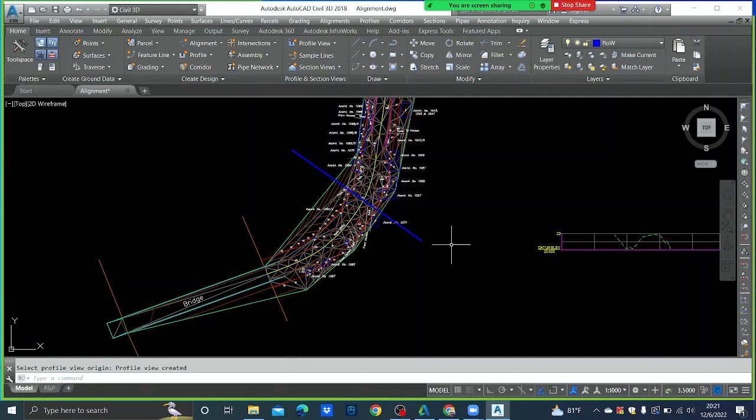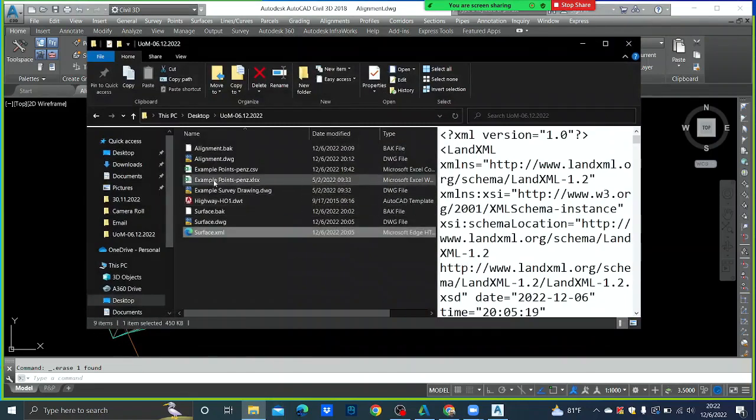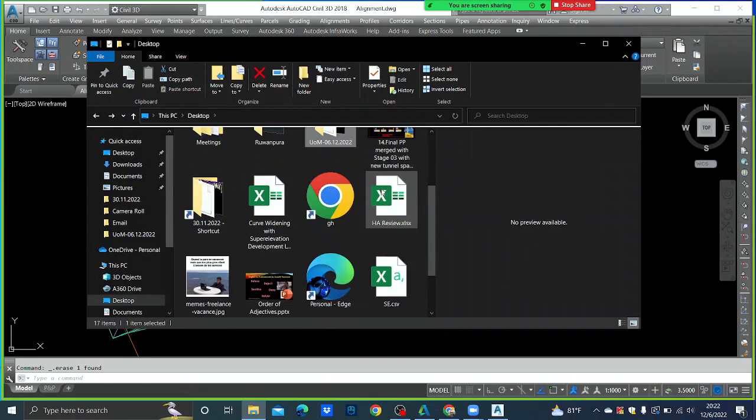Traditionally it is just like asking an engineer how much we will have to spend for this. So he's telling a value that need not be very accurate. Okay, but it is some approximation, right? I think now you understood. So we'll go to design the alignment. Before that, I have to tell you one thing. If you are going to design the alignment, you have to understand for each design speed with some particular super elevation, what should be your minimum radius. Okay, I think that you have studied these things. We'll see whether I'm having this one with me.